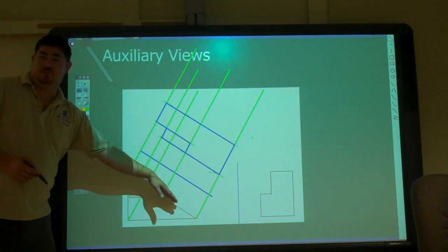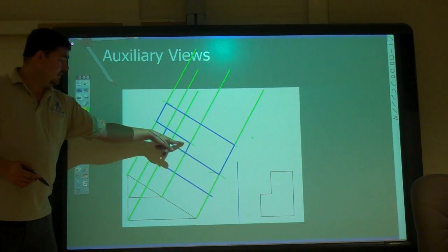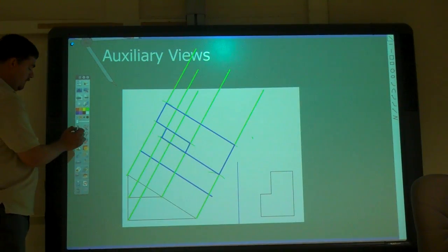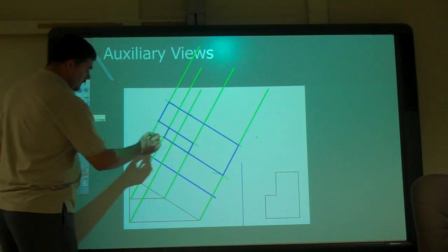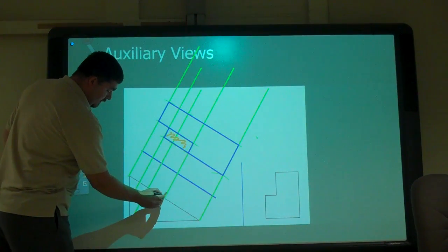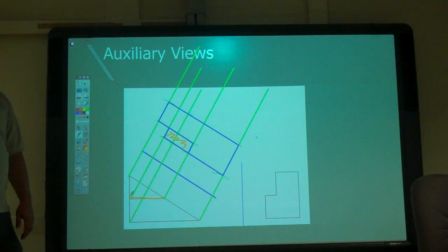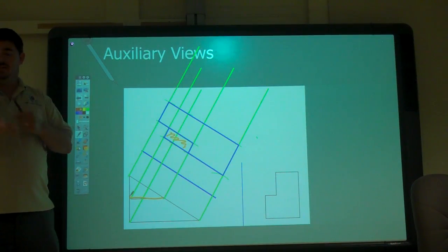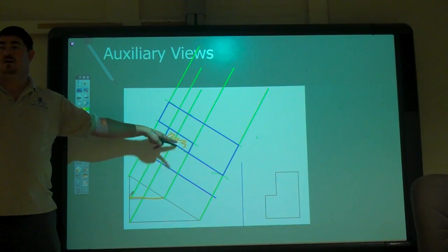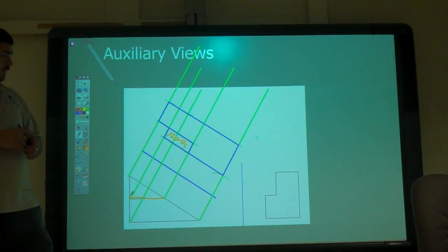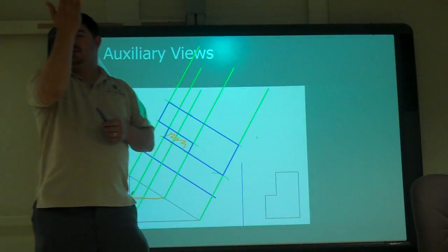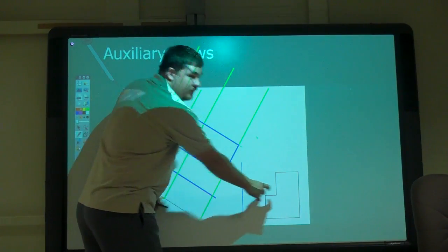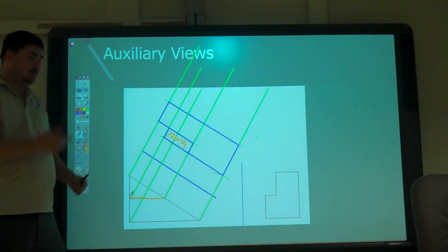But it's not on that front plane, because this right here is this surface, right? So that surface right there is that surface, but now since we're looking at it, that's not parallel anymore, so we're looking at this surface foreshortened, right? That's what it's called when you're looking at a surface that's at an angle to you, it's foreshortened. It's the same width on the right. Yeah, this width, the same as that one. But now we're looking at the 2 points on it.